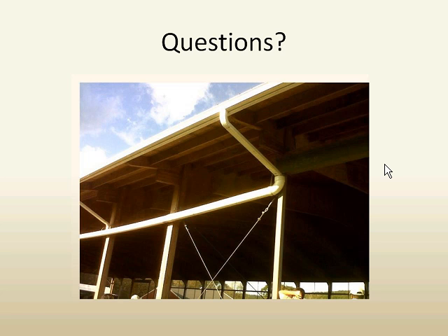I'm going to talk about roof water harvesting and requirements and a little bit about that then. But you're right, rainwater by itself is very clean. When the rainwater hits the roof, it can pick up contaminants, and so you may even get some fecal coliforms in that roof runoff water that you probably wouldn't want to drink straight.